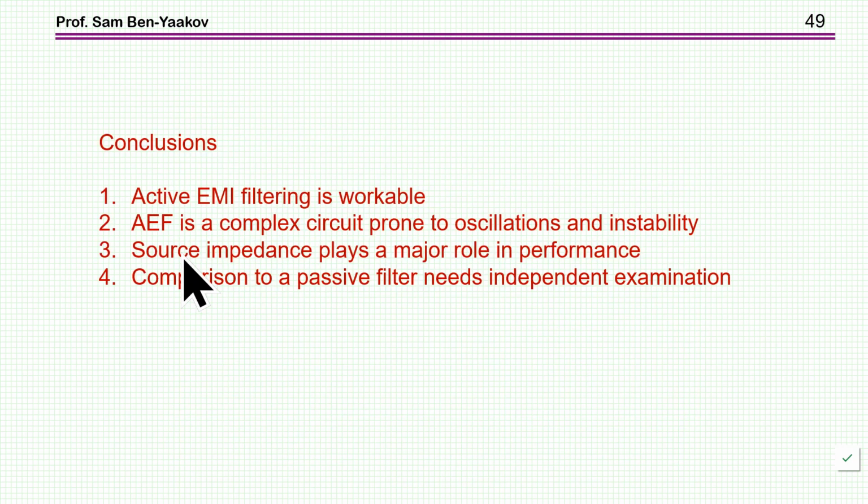So let me wrap up with some observations here. First of all, active EMI filtering is workable. I mean, you can operate it. It works. It's not something that you cannot operate, you cannot design, but it is very complex and prone to oscillation and instability, so it's not going to be a very simple task to design something which is stable, reliable under all operating conditions, and the spread of the values of the components.